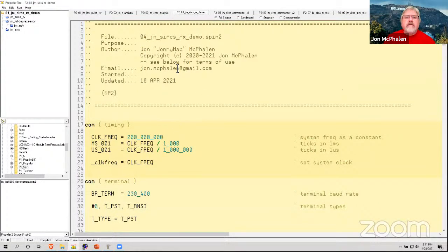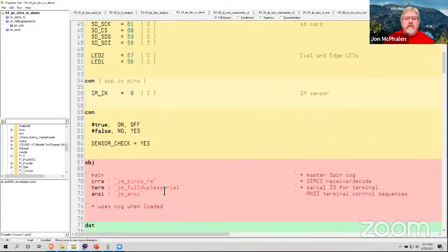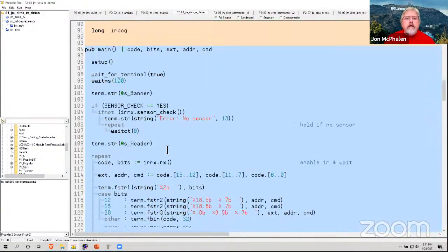So if we look at the top level code, one final thing, sorry, and this is a reliability thing. On this particular tagger, this one now has those same IR sensors. You probably can't see through the camera, but those little IR sensors we're using, we have two of them in here, so we have full directional coverage. The nice thing about these, you remember they go low, so they're just wired together because it's a wired OR system.